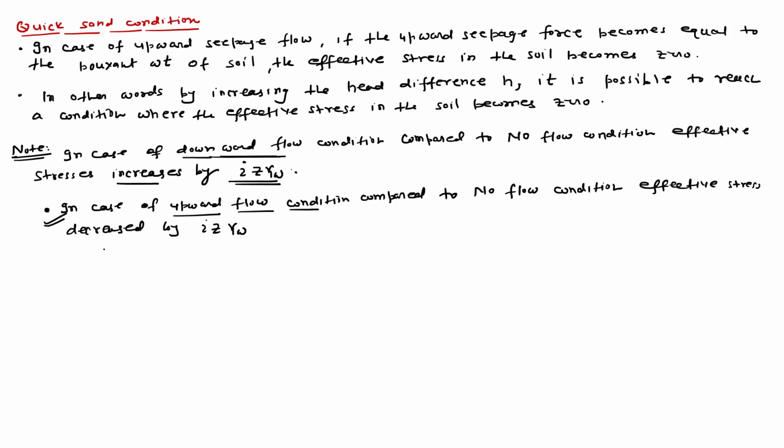So for quicksand condition, the effective stress becomes 0, and effective stress in upward flow is decreased by this much amount compared to no flow condition.